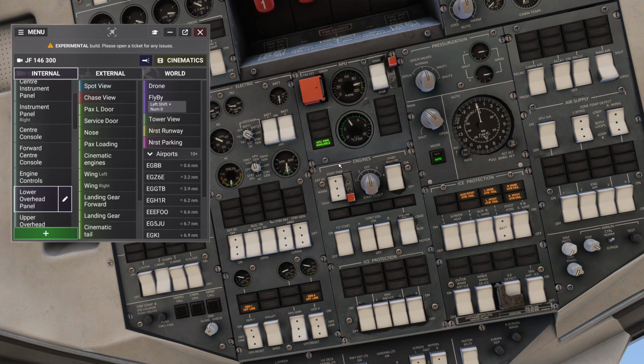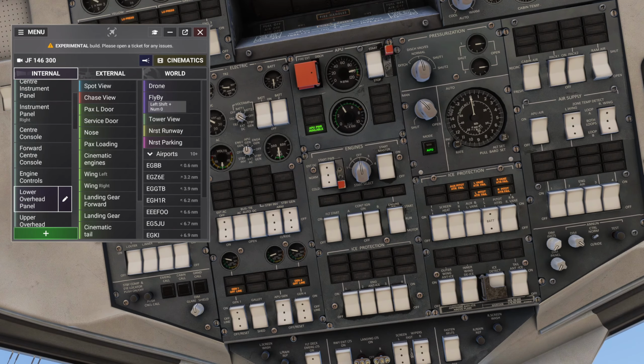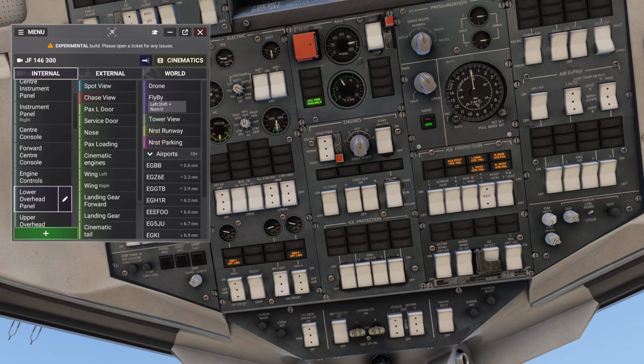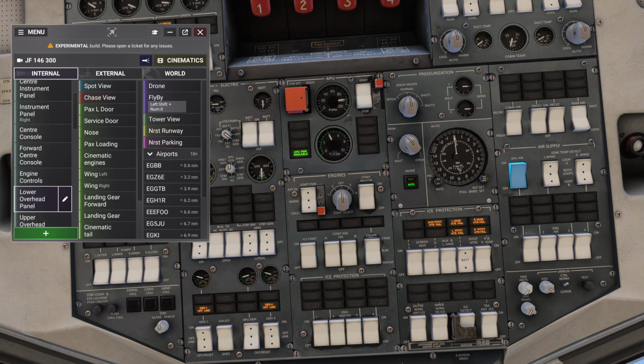Okay, do we have to set all the fuel pumps on? Because I missed that one. Yes, absolutely. It's important to have all the fuel pumps turned on, especially the ones feeding each engine to ensure a proper fuel supply. So definitely go ahead and set those, and then we can continue with the engine start procedure from there.